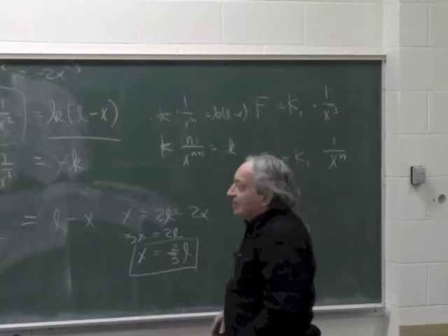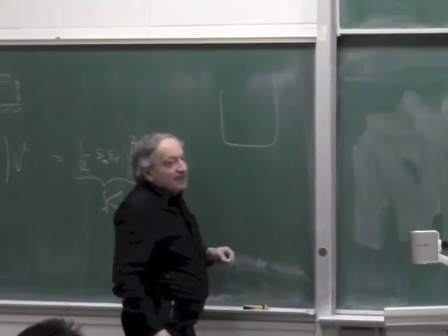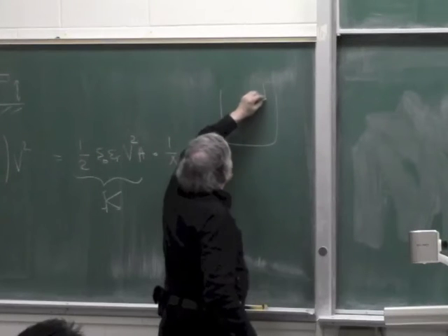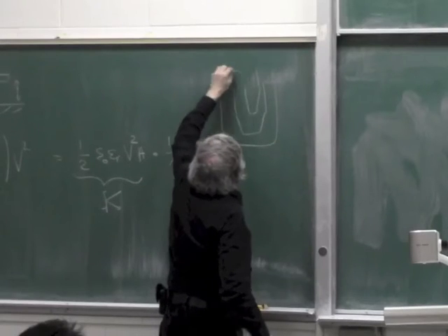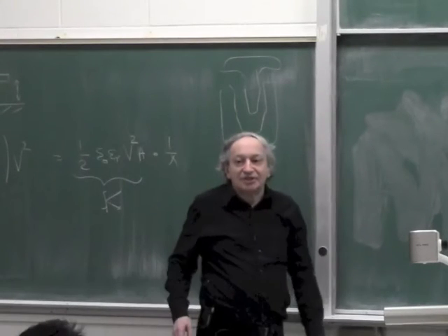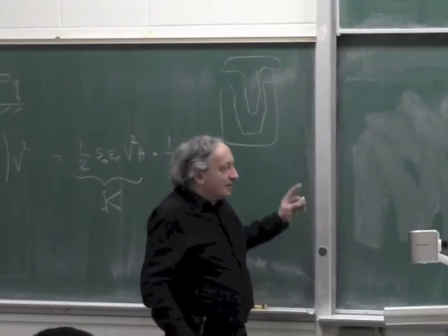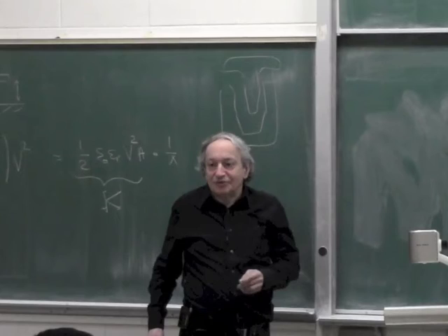For example, when you design a solenoid, a lot of times you design it not to be square law. So you design it with a special shape inside, something like this. You design it with some shape to try to linearize it a bit. And you do that, you can get any n, which doesn't have to be an integer. Okay? I'll show you in a minute another example of a solenoid where n is 1.5, not 2.